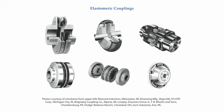Now, what would cause that? Well, in the case of the elastomeric insert coupling shown in the upper right, lower left, and lower center photographs, they are getting hot for the same reason as a mechanically flexible coupling, sliding friction. In the case of the rubber tire type coupling, whenever you cyclically twist or shear a material, you begin generating heat through molecular friction.